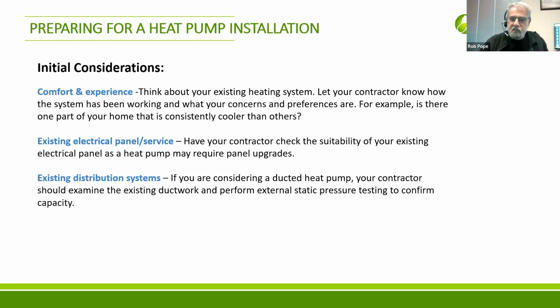Electrical panel service, as we discussed: we want to make sure there's enough room on the panel. Can we do it with the panel size that's existing? In new construction, we want to make sure that there's enough service being contemplated to incorporate the extra amperage draw of heat pumps. Perfect.